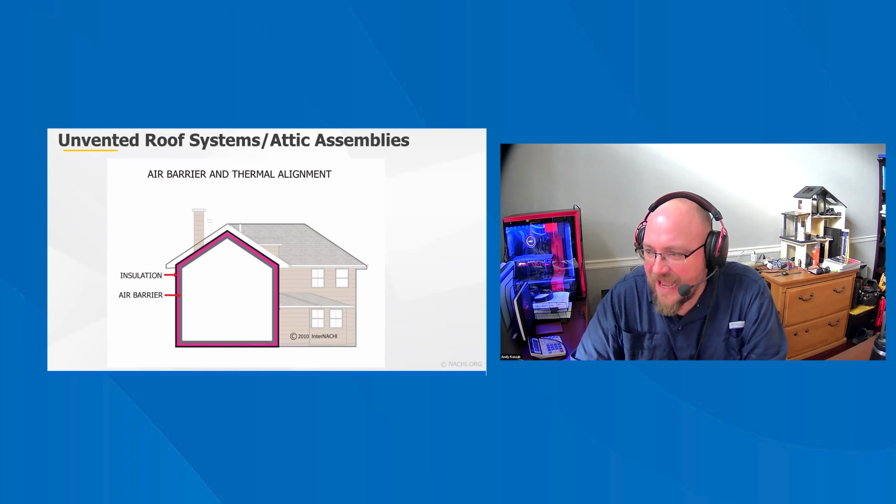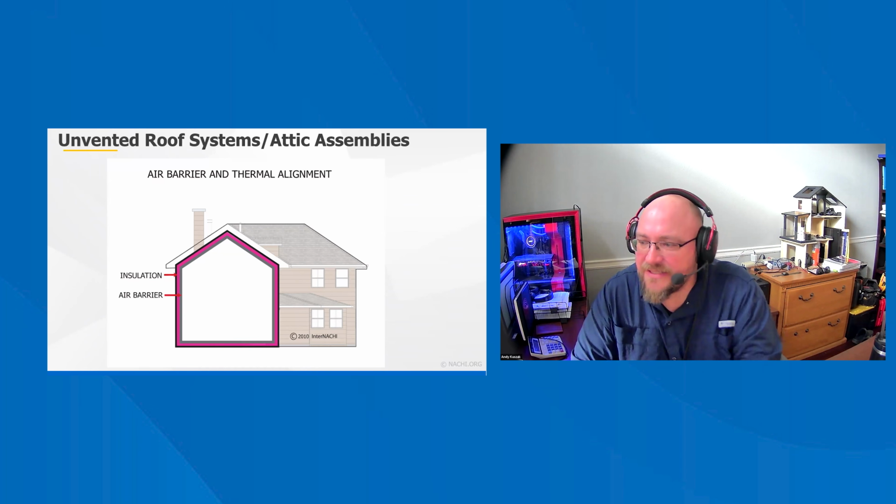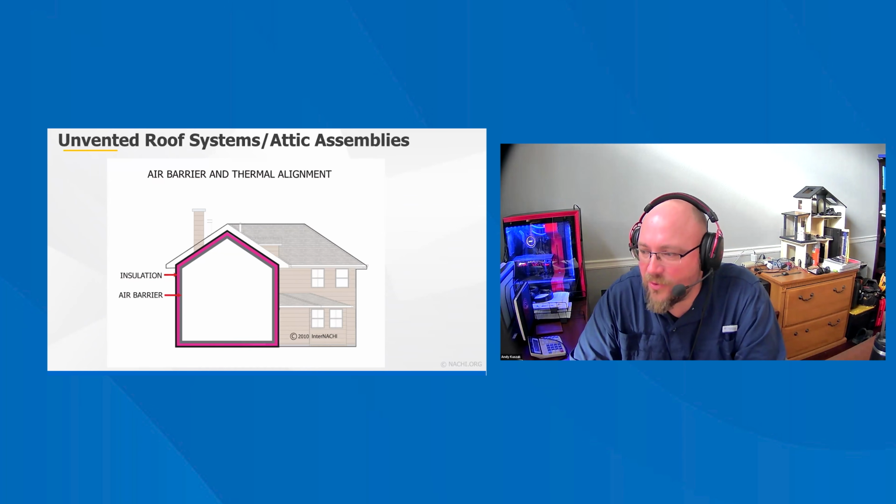Unvented attic assemblies should meet the following conditions. The unvented attic space must be completely contained within the building's thermal envelope. Interior vapor retarders must not be installed on the ceiling or the attic floor of the unvented attic assembly. At wood shingle shake roofs, a vented airspace of 1/4 inch should separate the shingle shakes from the roofing underlayment above the roof deck.